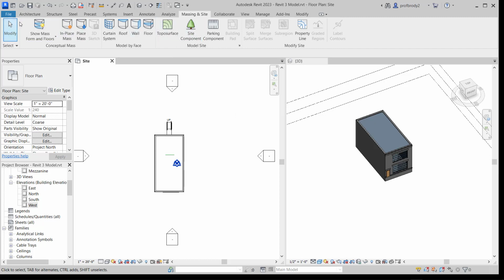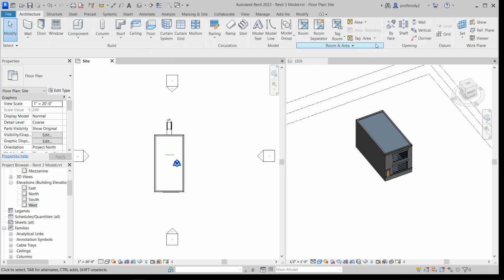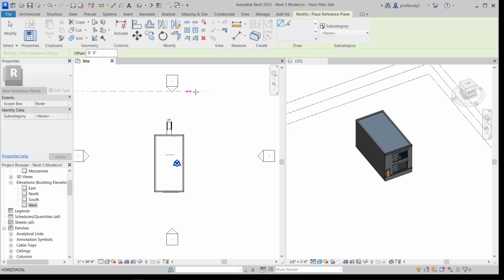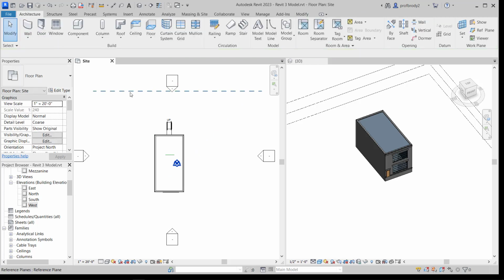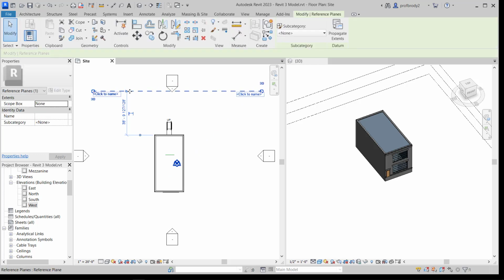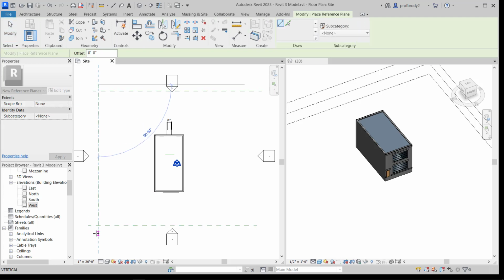points. I'm going to exit out of the topo surface for a second, and I want to draw in a couple of reference planes. It's just so helpful. Otherwise, you're just kind of clicking on points in space that, I don't know, it doesn't look nice and neat the way we like it. And I can copy these reference planes pretty easily, and you can, of course, also draw in site boundaries.